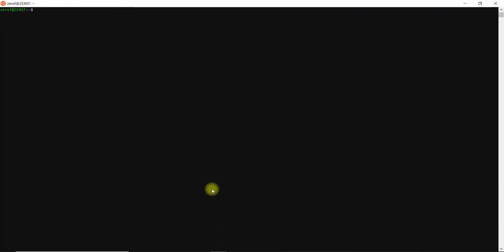At first, we need to get the files. For any simulation, we need the initialization, the constant, and the system. So let's go to tutorials. Open the Ubuntu bash. CD gives you the home tutorial. Now it should have OpenFOAM. CD, change directory, OpenFOAM. Press tab for accelerating it.